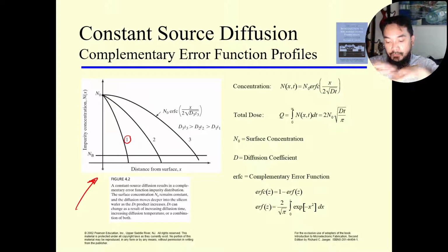Or you can use sputtering, or any other deposition method, as long as you can have a desired concentration of impurity atoms on the surface of your wafer. And then you put it inside a controlled chamber and heat it up from 900 to more than 1200 degrees Celsius. Then the impurity atoms at the surface will start to be diffused or absorbed into your wafer.